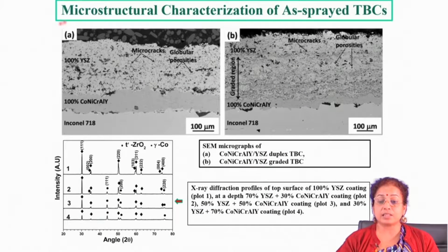Whenever these lateral cracks are present, whatever thermal stresses are developed get relaxed very nicely over the cracked points, and because of the very large stress, there is a change in monoclinic to tetragonal to monoclinic structure, and by this structural transformation the crack tip is also toughened.